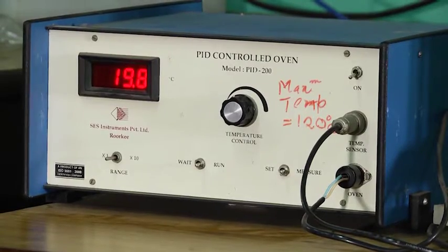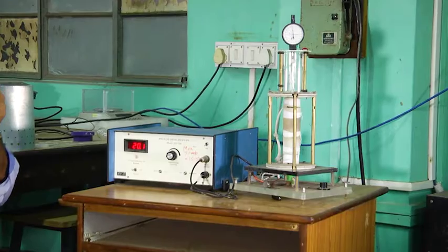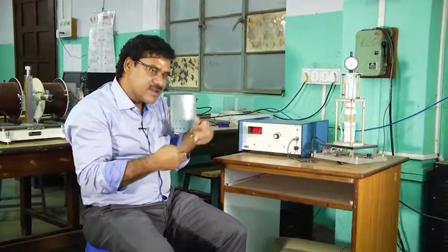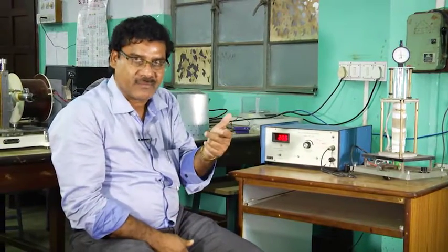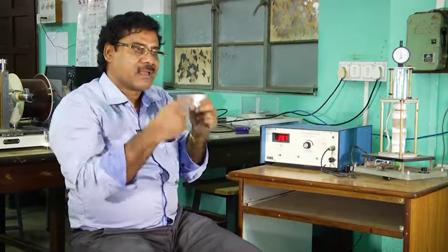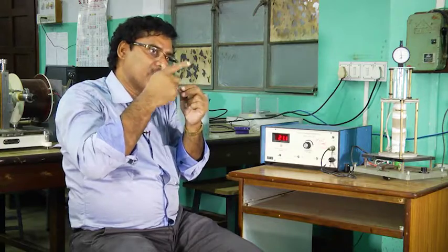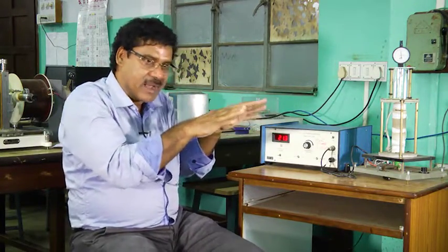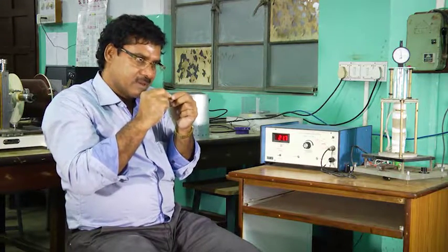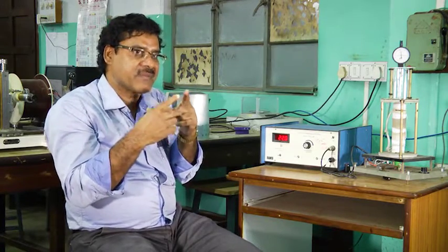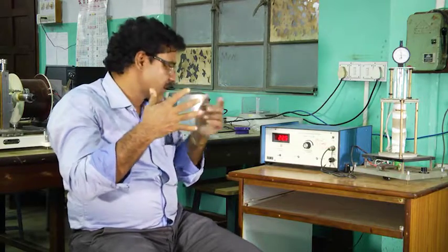19.7 now, 19.8 now. Okay. So, this reading is coming from the temperature sensor, and I have set it at 150 degrees centigrade. That means this change of temperature will continue until it reaches 150 degrees centigrade. So, PID control means it will automatically set at 150 degrees, and for changing the temperature, this system has a feedback loop. Every time it checks what is the set temperature and what is the present temperature. Okay. So, it is taking this temperature difference. If the temperature difference is higher, it gives power to the coil proportionally.